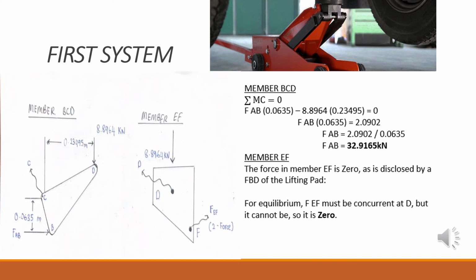A particular type of pump, a hydrostatic pump, is used to push oil into the hydraulic cylinder, where it is converted into mechanical energy. It is this energy that is used to power the hydraulic machine to lift the load off the ground.